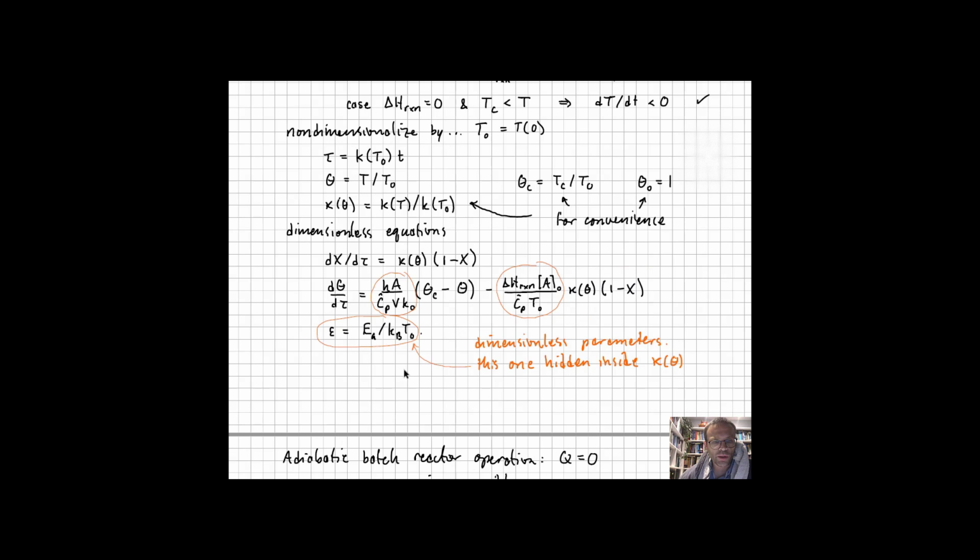There's one more dimensionless parameter buried inside this expression. Down in the kinetics, in the rate constant for this process, there is an activation barrier that has to be non-dimensionalized as well. We won't put in numbers for these things, but you can see that we take something that had 7 or 8 parameters and reduce it down to just 3 dimensionless numbers.